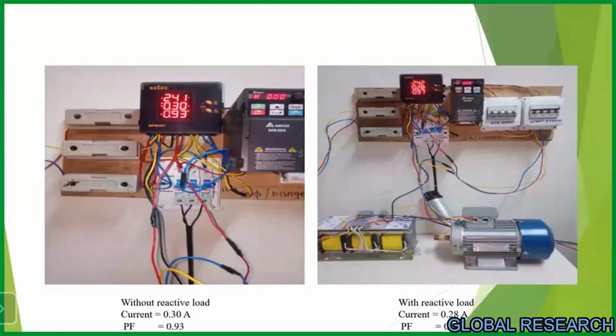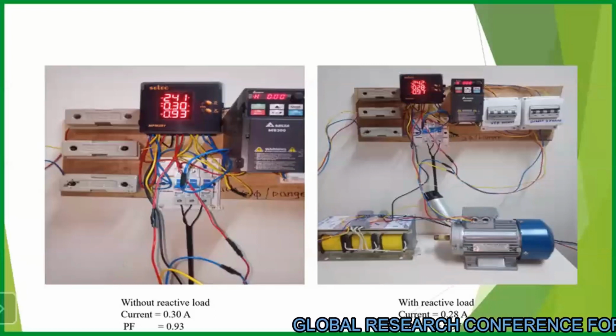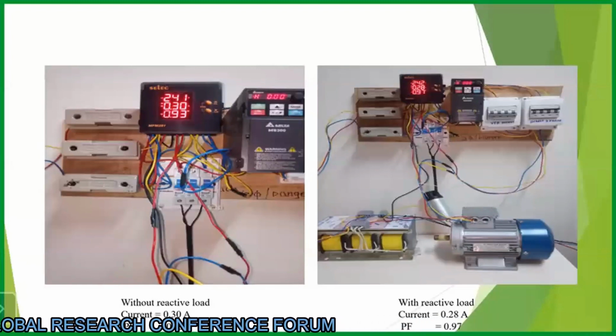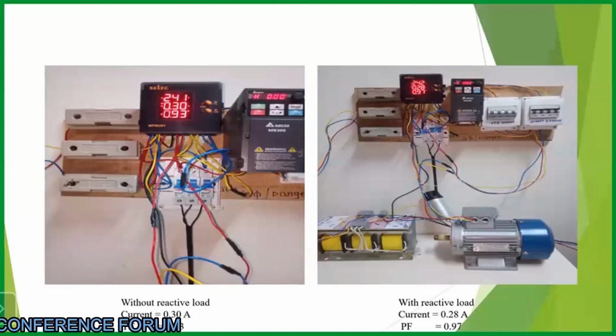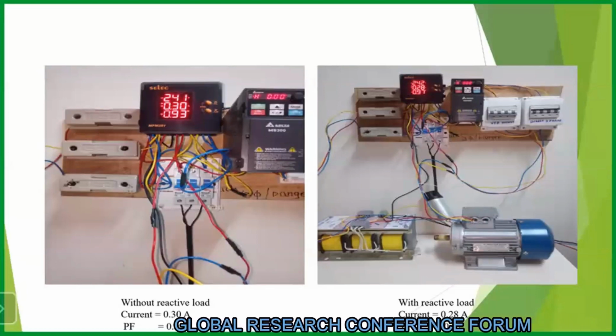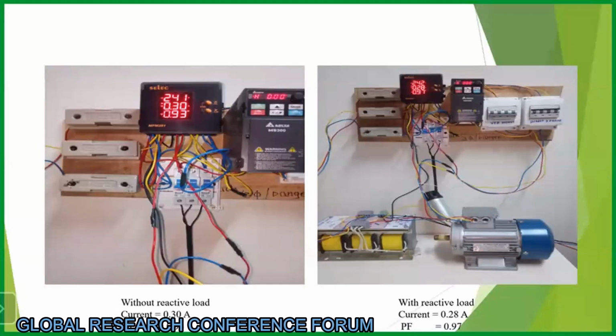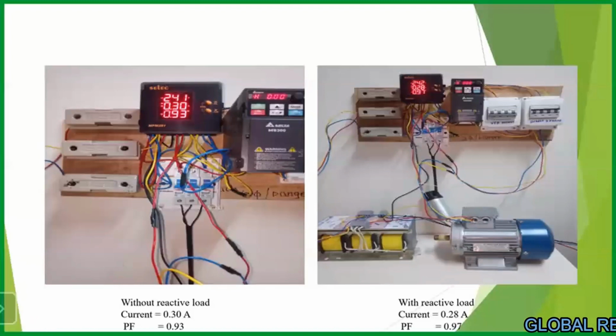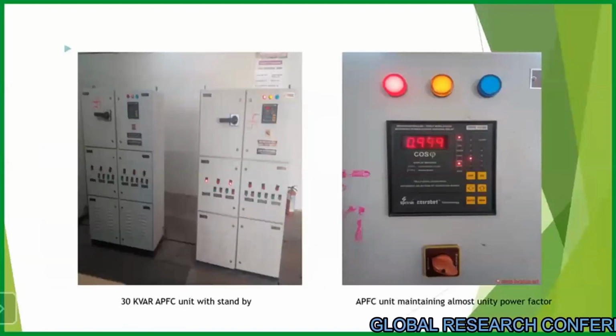In the other diagram, if I connect the 10 MFD phase to neutral reactive load, it indicates the current is reduced from 0.30 to 0.28, and the power factor is improved from 0.93 to 0.97. It means that as we connect the reactive load, the current demand decreases. Current demand is decreased. It is indicated here.